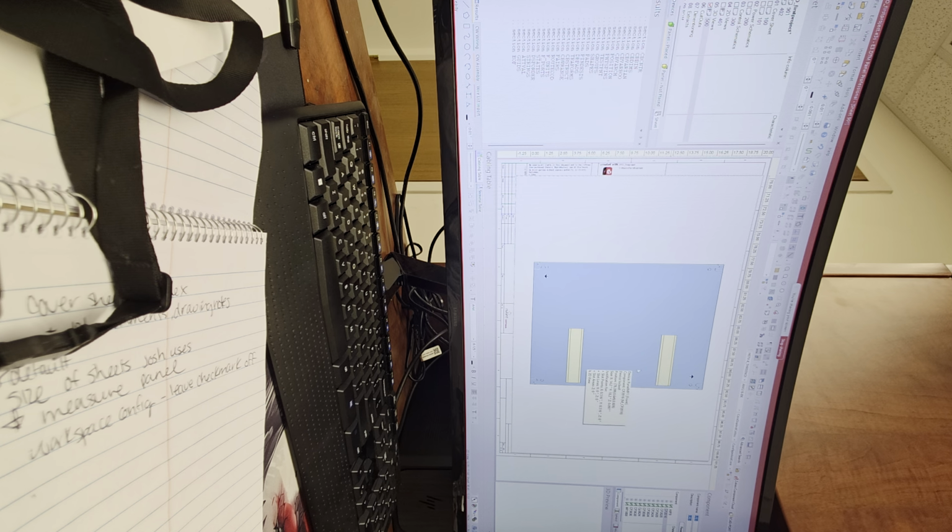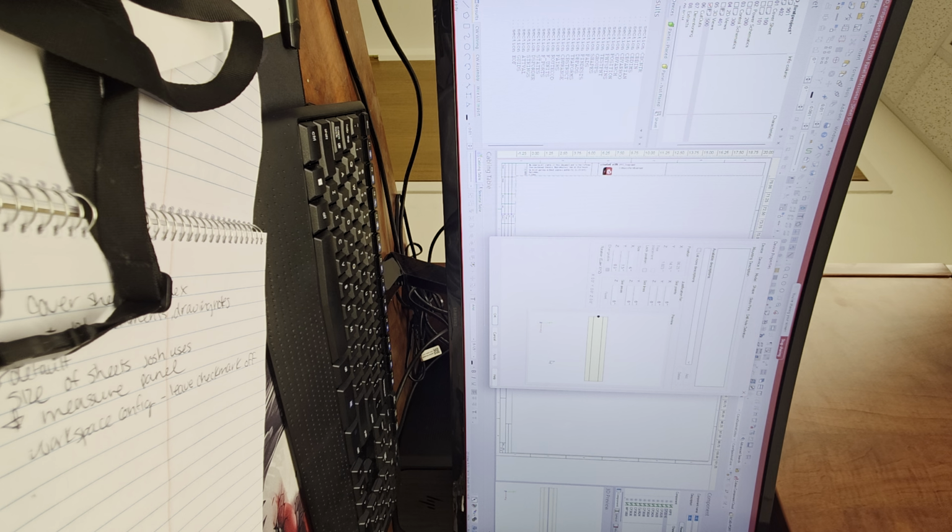So let's just say the very first step, you had the option to specify what the width was, right? So if you needed it 6 inches, we could have set 6 inches up front. You can also right click on this rail and click device properties. You're already in the shape steps. On the bottom left corner, you have the exercise. Let's say you happen to just move it perfect 6 inches. Wow. Your eye perfection is perfect. Okay? So that is where you can define the width itself.